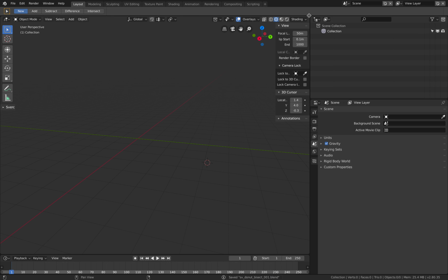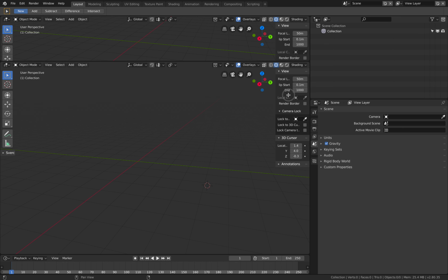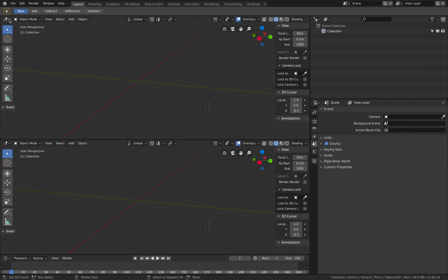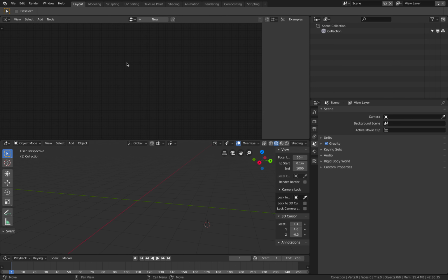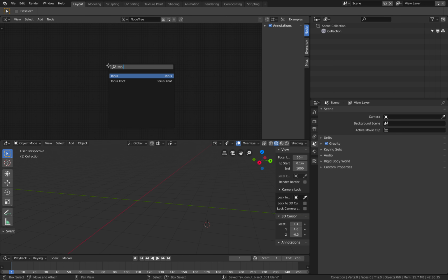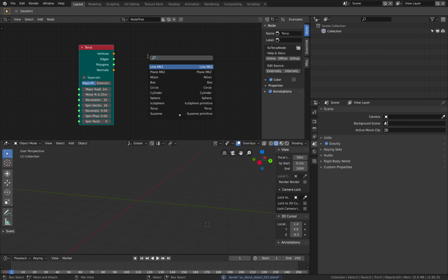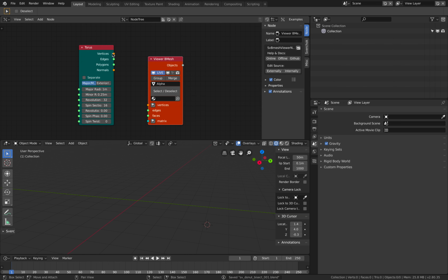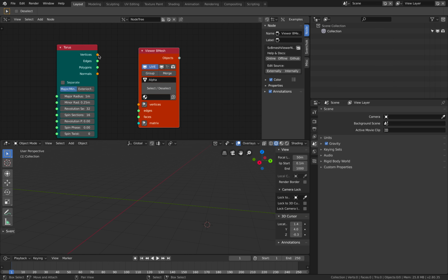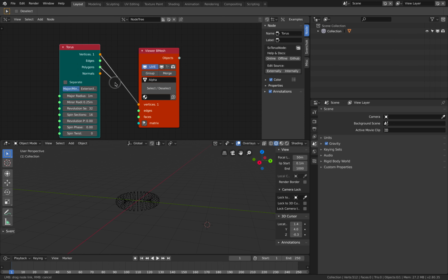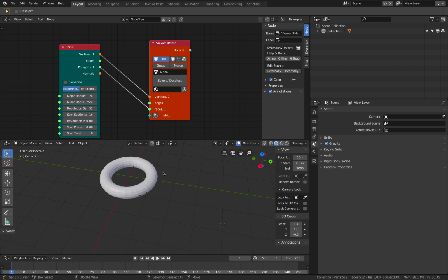So let's create a new panel. I'll just go to the corner here. If you are new to Blender 2.8, that's how you do it. Sverchok nodes, new, create a donut, and bmesh viewer. If you try to click on this guy, sometimes you don't get to the dots. So click on the name instead, or somewhere here. Okay, we have donuts, right?